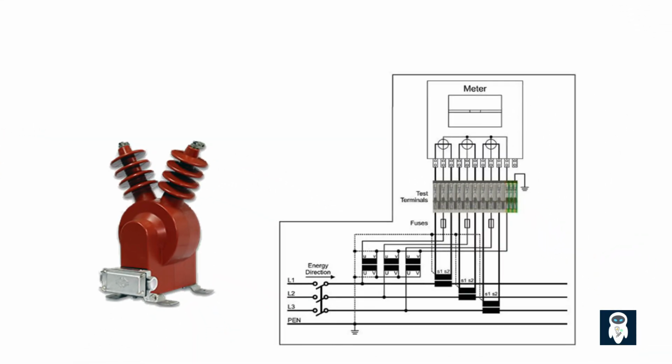Voltage transformers are vital for accurate voltage measurements. They step down the high voltage to a level compatible with measuring instruments, ensuring the safety of personnel and equipment during electrical measurements. Additionally, voltage transformers provide isolation between the high voltage and low voltage circuits, protecting sensitive equipment from power disturbances. What is a voltage transformer used for?